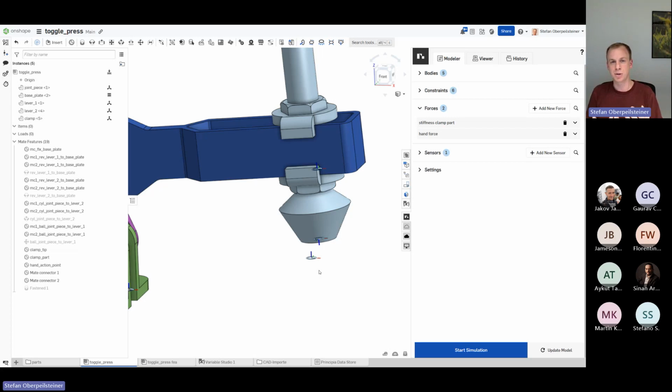So it's just something here against our world environment. In multi-body dynamics, you probably read this very often, when there's world or ground. This means this is something against the surrounding. The surrounding is something that cannot be moved, that is not deformable, etc. So that's the same here. The tip of this clamp should connect with the surrounding when there's contact. If there's some gap in between, nothing to do, no force, only in case of a contact.